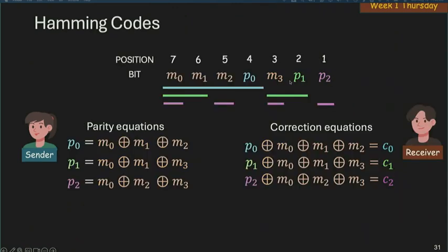Hamming code is just a way to put down 3 parity bits at those particular positions. The idea is very much the same as a 1-bit parity, but now we're using different parity bits to monitor different positions, so that each position affects different parity bits. And then by checking the correctness of all the parity bits, you can actually locate where the error happens.